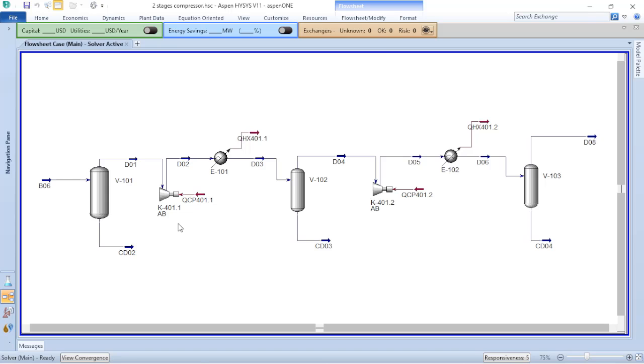Remember to consider the amount of power needed as shaft power for the rotating compressor, and also the amount of power needed to have the cooling of your stream. The heat power or the heat flow is different from the mechanical power. So make sure not to sum up things that are different. You need to transfer the thermal power to shaft power so that you can have the estimation for the power consumption.